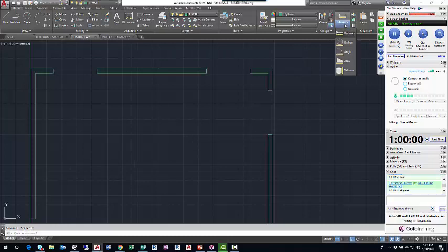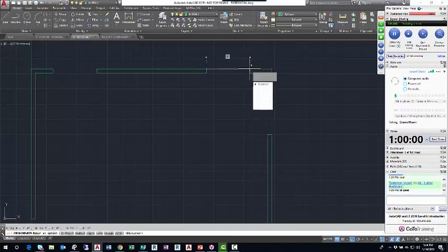I'll open up the measure suite, and you'll see this distance tool. I'll click on distance, and then I'll use my object snap, and I'll snap to the endpoints of this opening, the outer endpoints. If I go one outer and one inner, it might give me an inaccurate measurement. So I'll go one left click, two left click, 3 feet. That's a 3 foot opening.